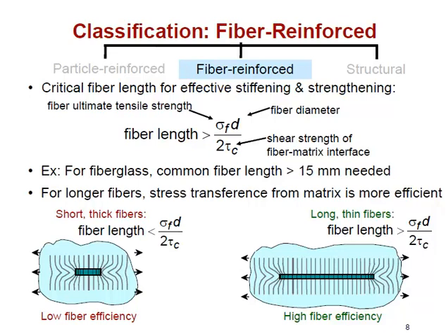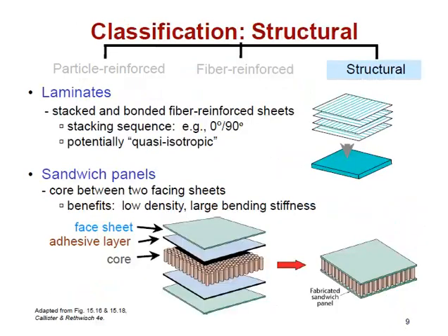So if you're adding a fiber reinforcer to achieve higher modulus or higher strength, there is that minimum length that you need to be effectively getting your money's worth from the reinforcer. And as a rule of thumb, just a quick benchmark for glass fibers, for typical diameter glass fibers, you'll need about 1.5 centimeters of length in a chopped discontinuous fiber matrix composite to achieve that.